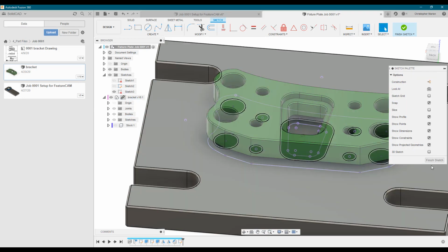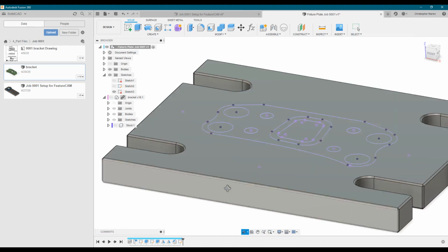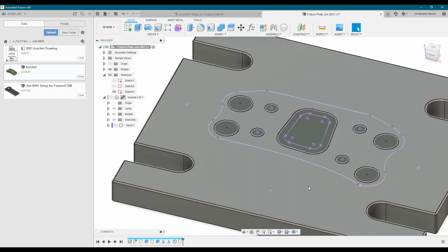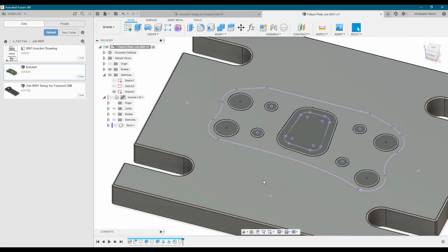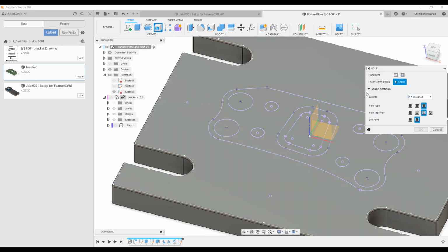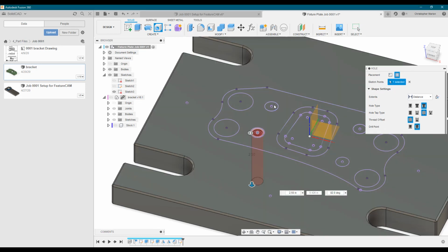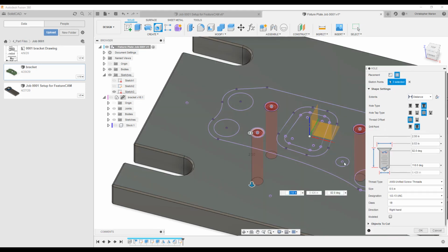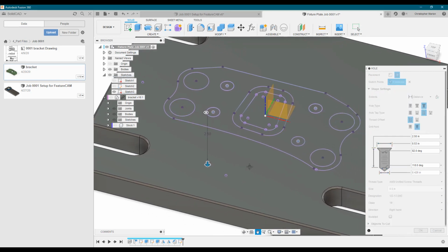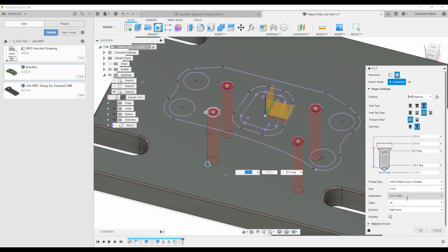And we're going to finish the sketch. Okay, so I brought more geometry than I needed, but that's okay. So let's go ahead and create a hole. And we're going to create a tapped hole at these locations. And it's basically going to cut a 1/2-inch threaded hole through my plate.